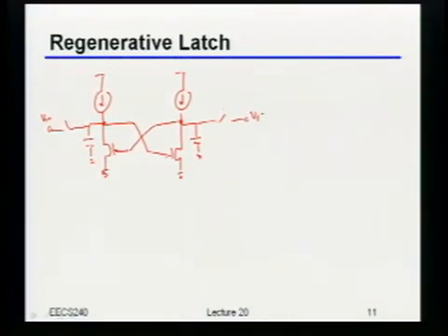So what I'm going to do is say, initially, let's say at t less than or equal to 0, I'm going to turn on those switches, and let's call these C here, I'm going to initialize the caps to VI plus and VI minus. Okay? So that's how I'm going to force the input in. Then once I actually want to get the answer, I turn off those two switches.